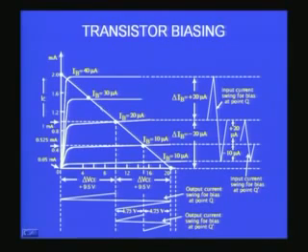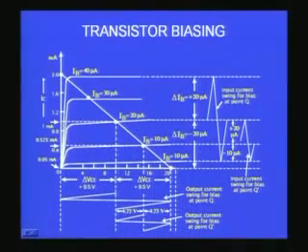So you find when this happens, corresponding to these 2 points, the collector current also changes. As you can see, this is around 1.4 or 1.5 milliamperes, and this point corresponds to about 0.5 milliamperes. So when this base current changes by a very small 10 microampere range, the collector current changes from the operating point of 1 milliampere to nearly 1.65 milliamperes and to 0.5 milliampere, nearly about 1 milliampere plus or minus 0.5